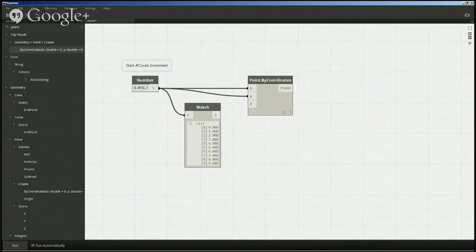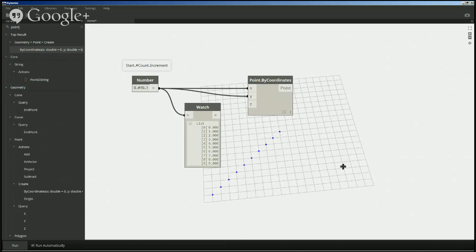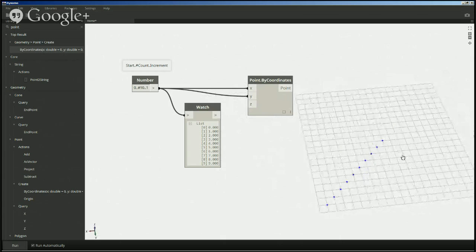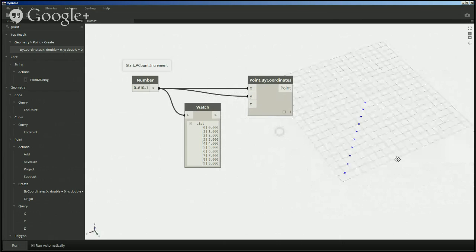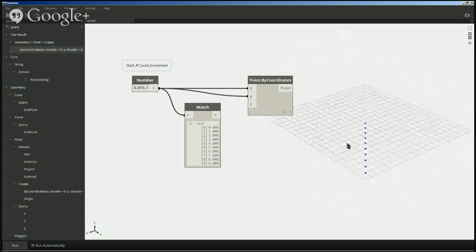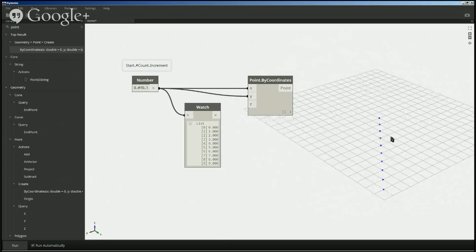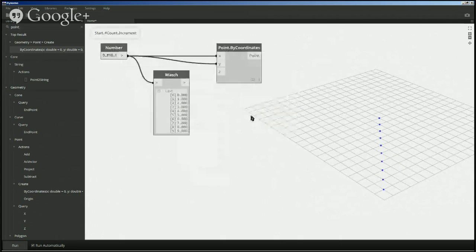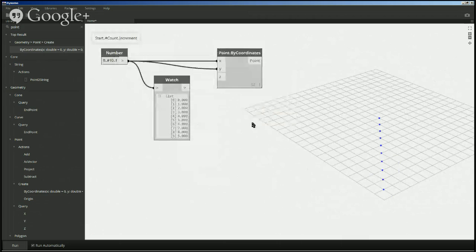and turn on the background preview of the workspace. So I'll just go ahead and turn that on. To navigate the background, you can use Control G, and you'll see that the middle mouse down will pan, the right mouse down will orbit, and you can zoom with your middle mouse scroll. So returning back to the definition, I'll just hit Control G once again, and you'll see that now we're back here navigating within the definition.